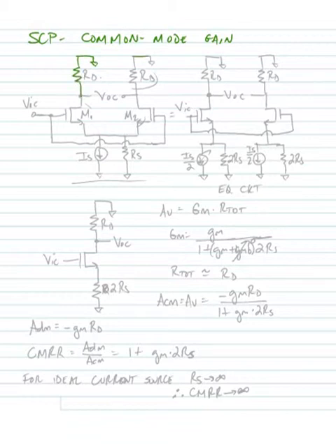We'll draw it similarly to our small signal circuit for the differential mode gain that we drew, only we're going to put a common mode voltage in, which means we're going to put a VIC in. We're going to measure the output differentially, VOC. And remember, ideally, we'd like to see nothing come out for our common mode input.